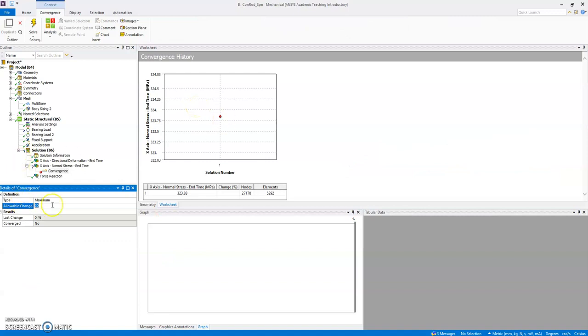Okay, so that convergence, we have done it, I think, already in week 2, but you need to change the allowable change to something a bit lower, otherwise it will accept it too quickly. So let's say 4% here. And last time we did it manually, because it was quite interesting to study it like that, but it's also possible to actually automate it.